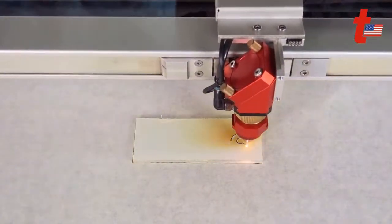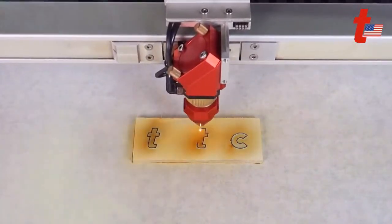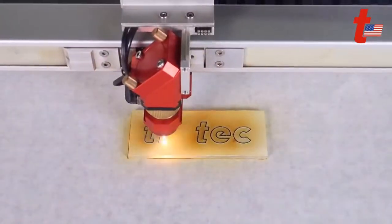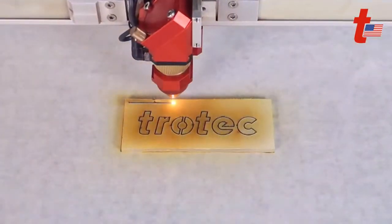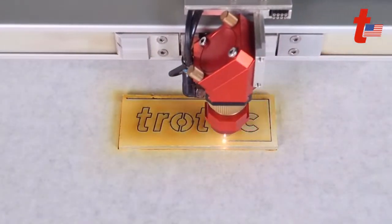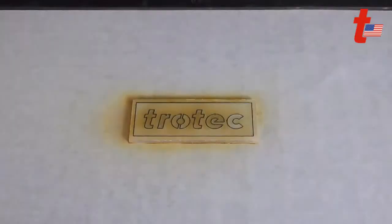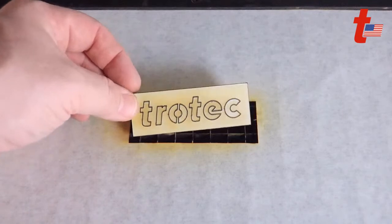So I've left the film on both sides of the piece of polycarbonate, and then when we go to cut it, you can see what comes out of it. This is why that film needs to be left onto the surface, because it'll stain the surface of the material. It is a very dirty material to work with, especially when cutting like this. So you see here exactly the reasons why you would need a vacuum cutting table. I've masked off the excess cutting table, so I've got a vacuum going through it, pulling that debris away. I'm also using air assist, punching it so that it doesn't damage the lens.